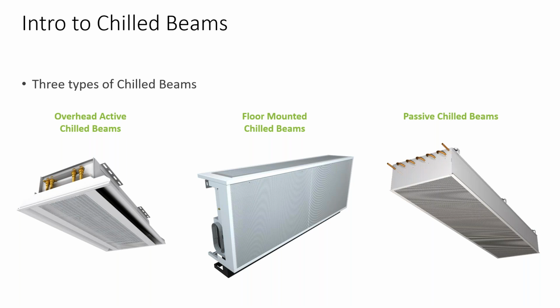Now there are various versions of it, and it has evolved over the years into several main types of chilled beams. The first and most common one is the active chilled beam, and the active portion of that is essentially the primary air component, the fan-forced supply of the primary air pushed into that chilled beam plenum. That is what creates the induction. We'll talk about that science in a slide or two. Essentially, this is an active beam, meaning you've got a primary air supply to it, and a fan pushing and creating the static to push that air into the beam.